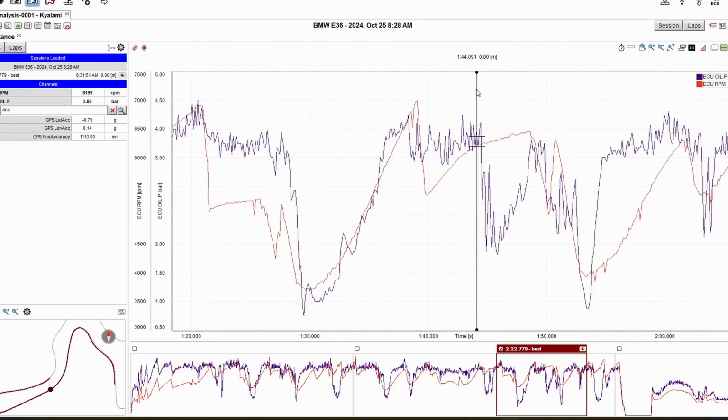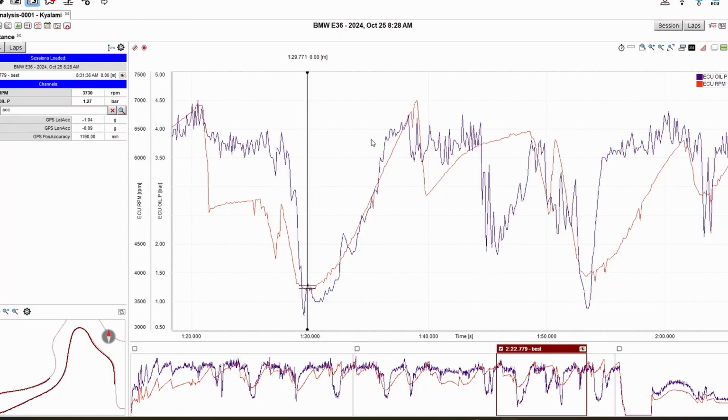And then I look at it again here on the brakes. And what that tells me is something is happening where the oil is there, and then all of a sudden it's not there. And it's not as though it picks up a bubble where it goes away and it catches pressure again. That would be this kind of spike here. You'd see it like a spike like that. A drop and a spike and a drop and a spike. No, we're seeing it from a point of view where you see pressure, then you don't. And I thought, wait a minute, it must be sloshing.